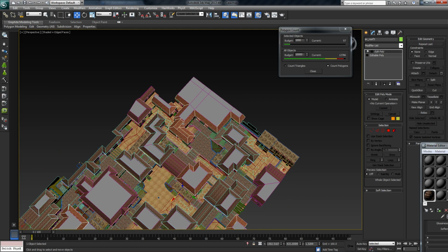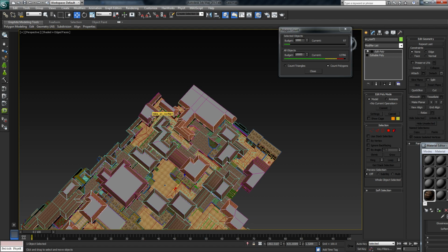Well, there's something wrong with this roof. Click, clean it up, export it as a separate in-place edit, then go and correct your block file to update it with those corrections. So eventually, what happens is everything is replaced.